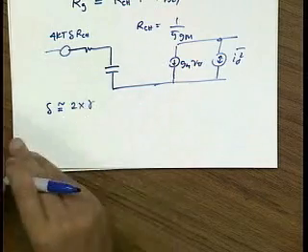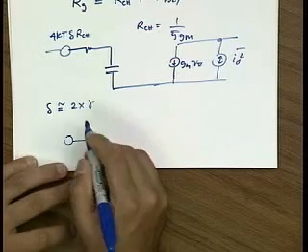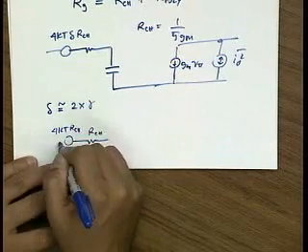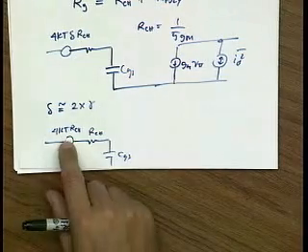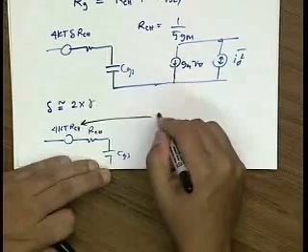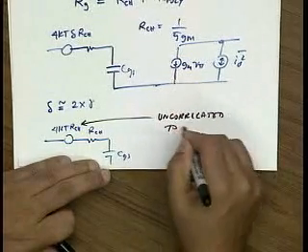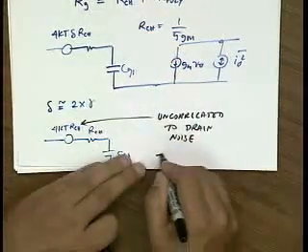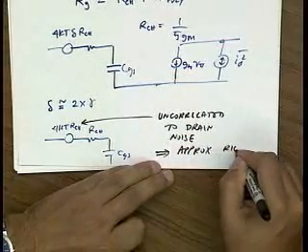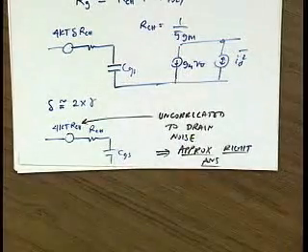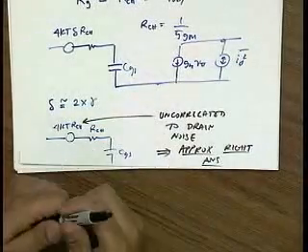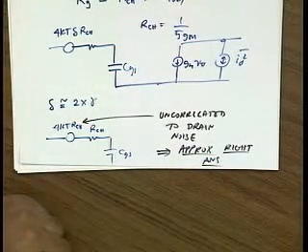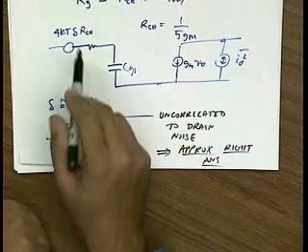Now the nice thing is that if, on the other hand, you assume that this resistance is a white noise of just 4kT R channel, so delta, I'm assuming delta is 1, and assume that this noise is uncorrelated to the drain noise, then you get the right answer, or approximately so. So it turns out that the easy solution gives you the right answer. If you do it the hard way and take the correlation into account and everything, you get a slightly more accurate answer, but believe me, it's a lot more painful to arrive at. So this approach is a very nice way of handling the MOS gate-induced noise. You just assume it's uncorrelated and you get rid of this factor delta. Okay?